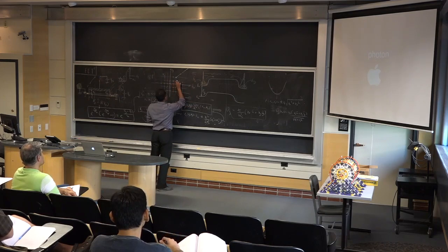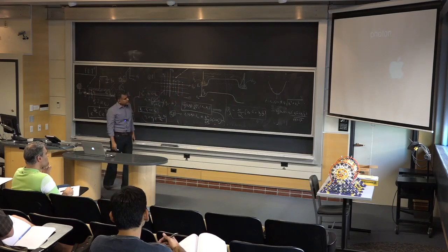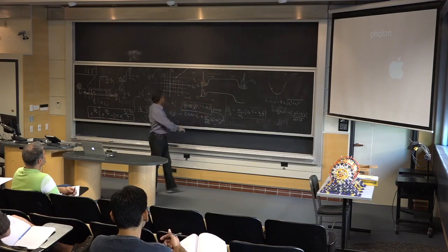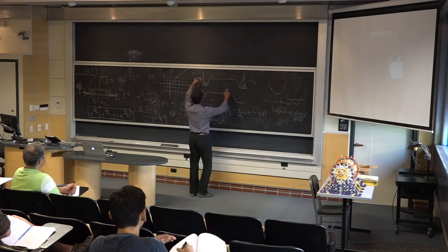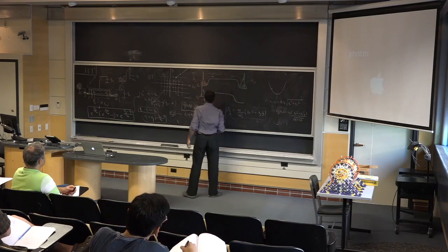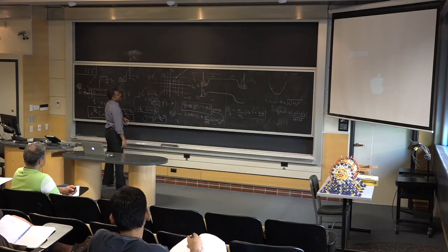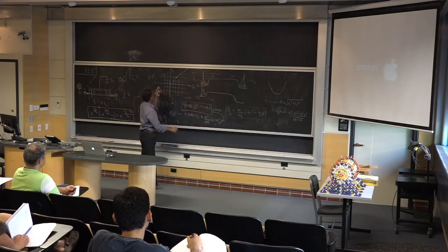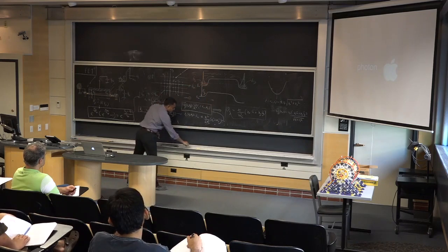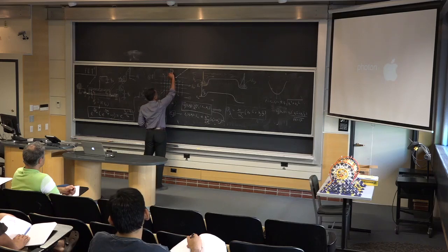So you can join it from here and draw. So you have all this. If that's the velocity, what does it really mean? Let's connect it back to the problem at hand. We have injected carriers from the source, injected carriers from the drain, and what we are saying is the carriers are filled all the way to a certain distribution function. So the right-going carriers, let me now use a little color. The right-going carriers, I have filled it. Maybe I'm going to draw a little half circle like that.